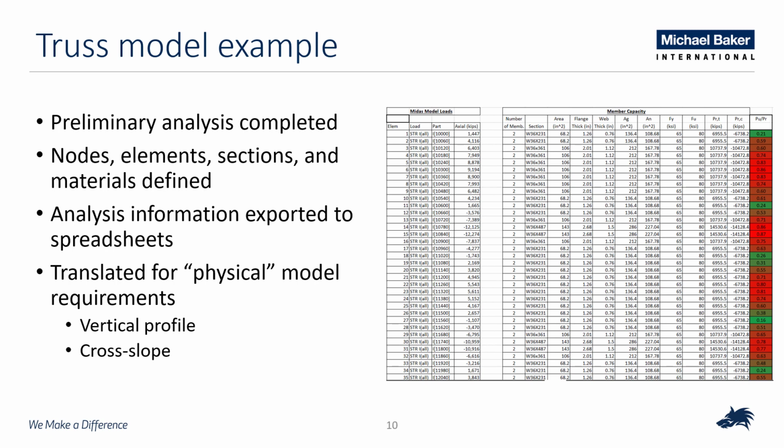So in terms of what we need to do, we have the analysis model. We do not have vertical profile. If you're familiar with bridge analysis, typically we don't include the Z elevation within our models, right? That's typically ignored, but we need that for a physical model. So we were able to pull in our profile information and add that to it so we have accurate not only X, Y coordinates, but Z coordinates as well.